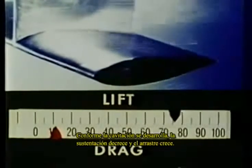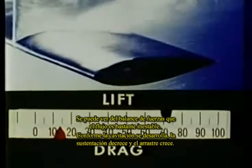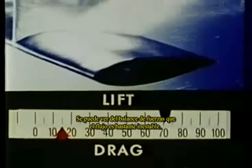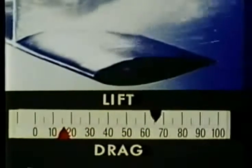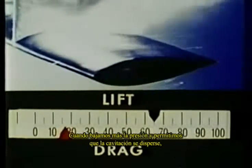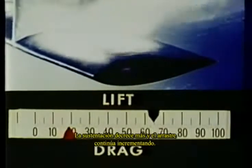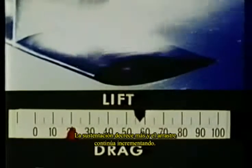As cavitation develops, lift decreases and drag rises. You can see from the force balances that the flow is quite unsteady. When we lower the pressure further and allow cavitation to spread, the lift decreases further and the drag continues to rise.